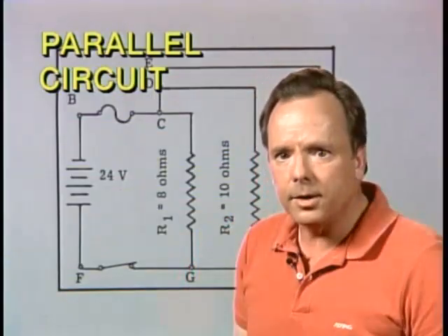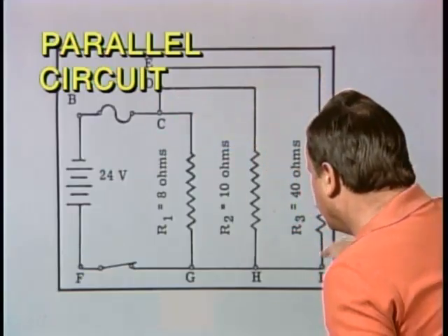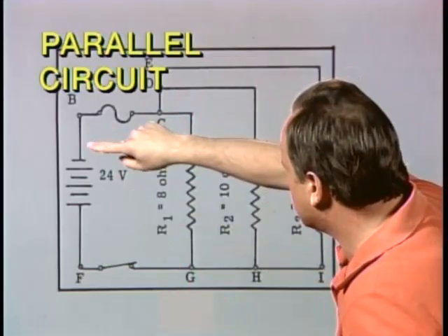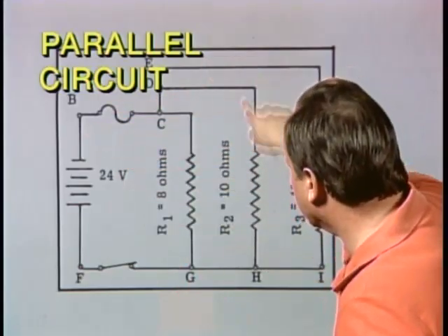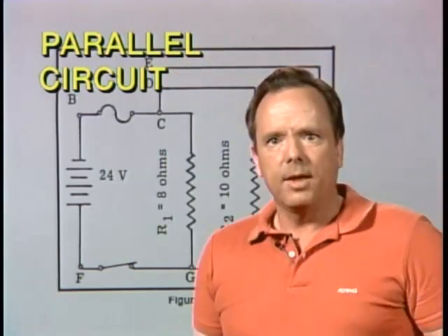in this case. So if the total circuit works out to 2.52 ohms and the resistor in this circuit is 2 ohms, then what's left must be the total resistance of the battery, the internal resistance of that battery, and it's 0.52 ohms. All we have to do is subtract, and we've got it figured out. All right, let's do another one.